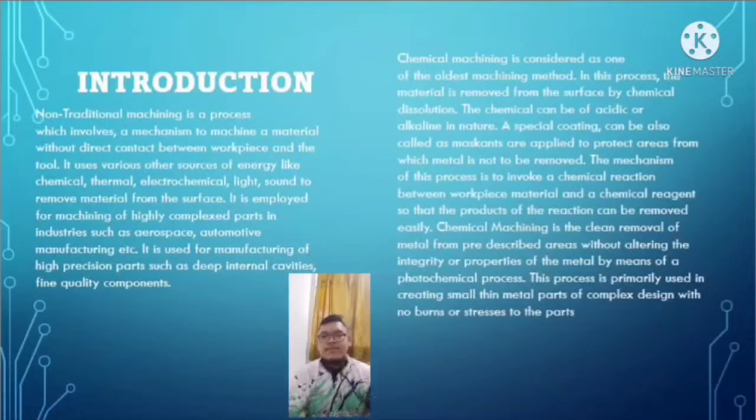Chemical machining is considered as one of the oldest machining methods. In this process, the material is removed from the surface by chemical dissolution. The chemical can be of acidic or alkaline in nature. A special coating, also called maskant, is applied to protect areas from which metal is not to be removed. The mechanism of this process is to invoke a chemical reaction between workpiece material and a chemical reagent so that the product of the reaction can be removed easily.